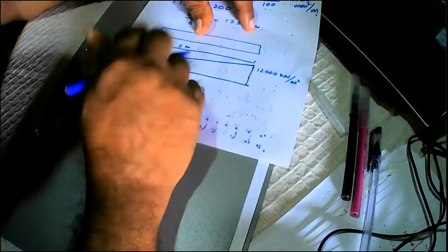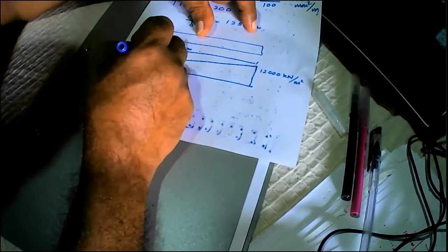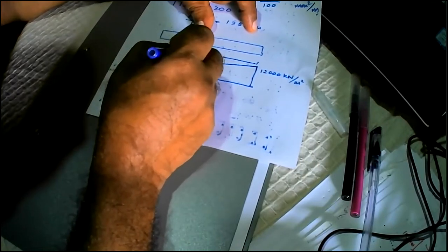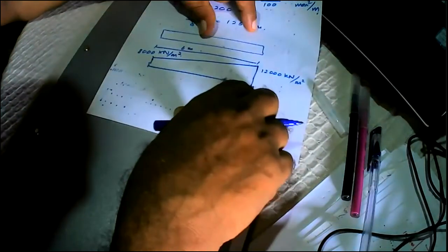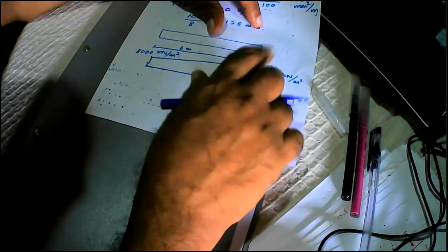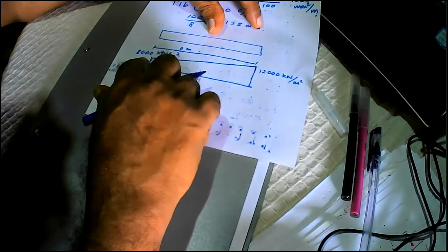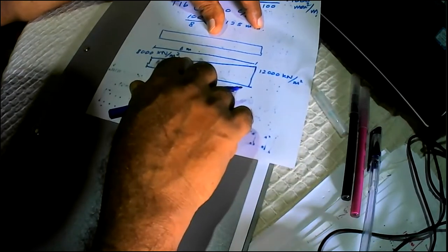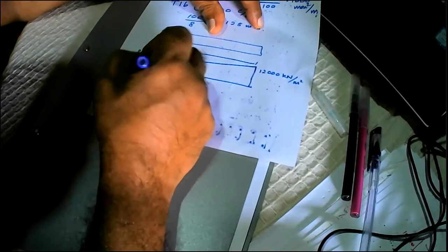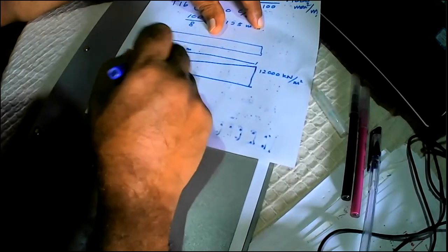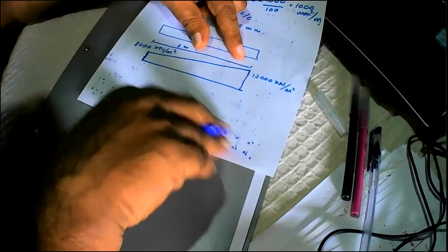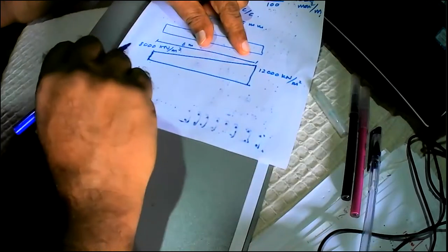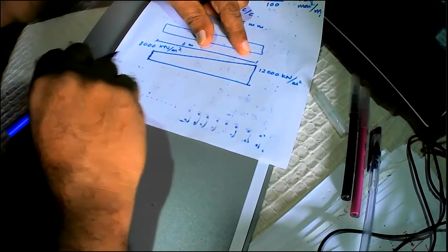So on the other side, you might get something like 8,000. But that value is not important, because what happens is the wind forces can reverse. So if you get 12,000 here, you can get 12,000 on this side also. Right? So this minimum stress will be significant if you get tension here. But if you are getting compression, the minimum value is not very significant. But if you are going to get tension on this side, then the minimum value will be important.